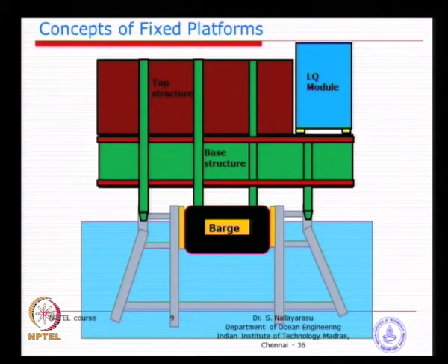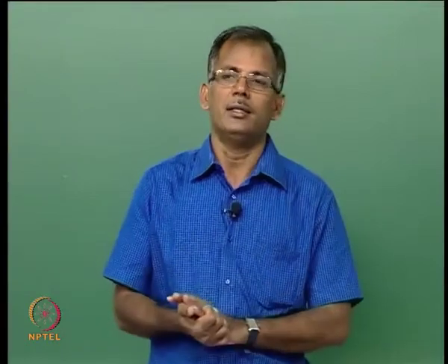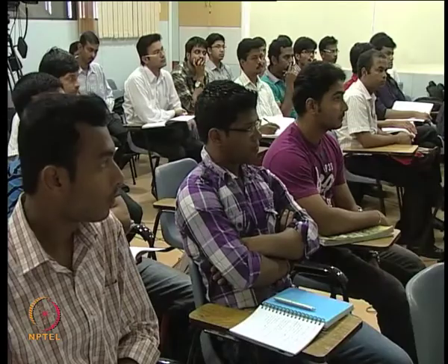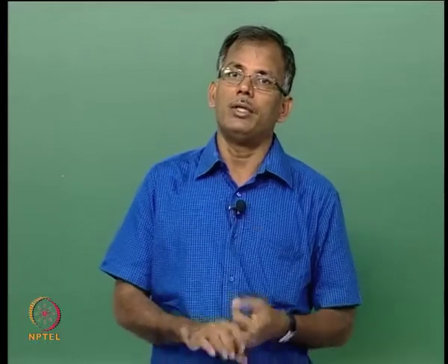So, basically in this design activity, before the structure is designed, you need to perform a naval architecture analysis, which is basically a motion response with such a big topside on top, and then the sea state to be determined. What is the limiting sea state in which you can actually do this activity? You will do a reverse calculation instead of a forward one, because everything else is fixed: the barge is fixed, the topside is fixed, the location is fixed. What we want to find out is during which days we can go there and start installing this platform.